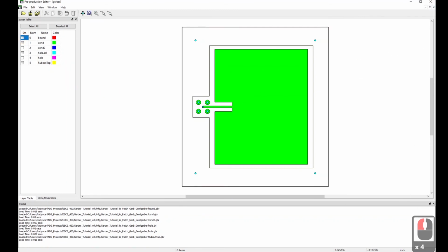And by default, this usually saves the Gerber files. It'll tell you where it saved it if you do the file preview. But you see that it's going to be in whatever directory that you're working in, manufacturing, then the name of the file, Gerber, and then you'll have your Gerber files.